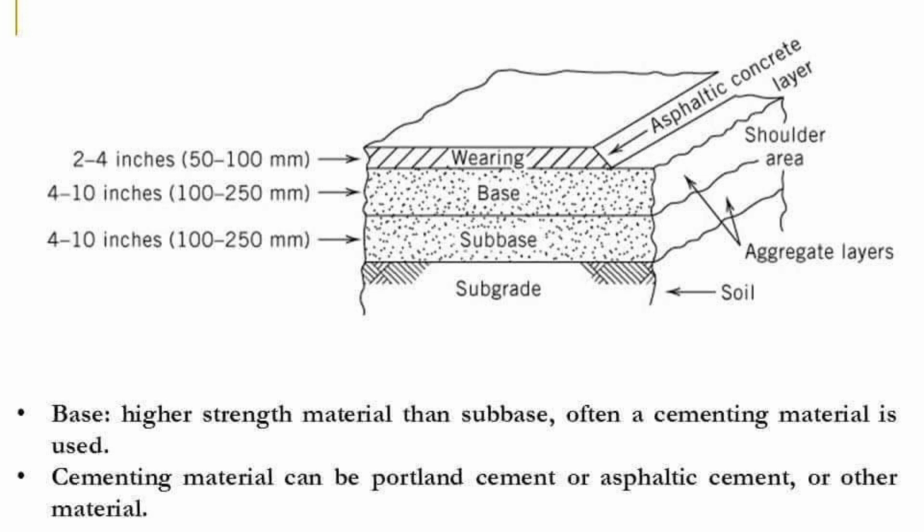Then you convert this CBR value into the modulus of resilience, MR value, and then you will have a structural number. From this structural number, you can calculate the layer thickness for the asphalt layer, for the base or asphaltic base, or sub base.